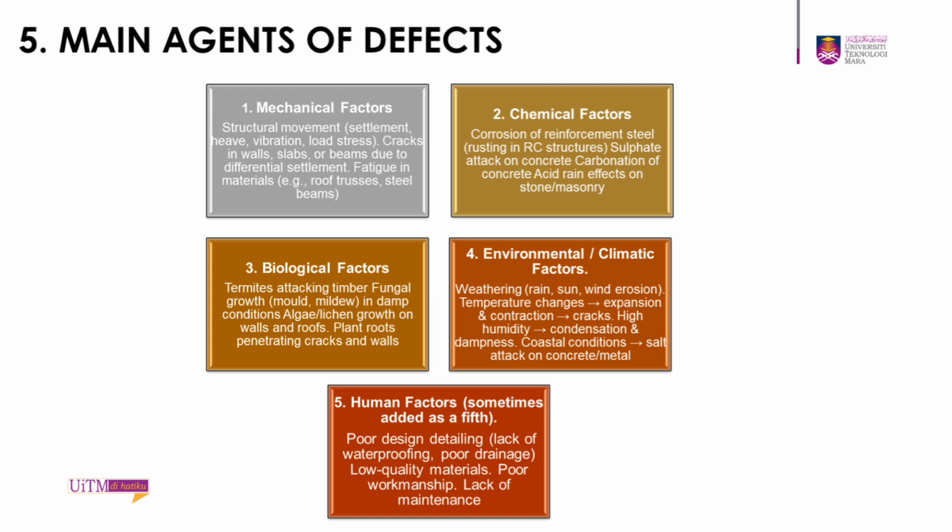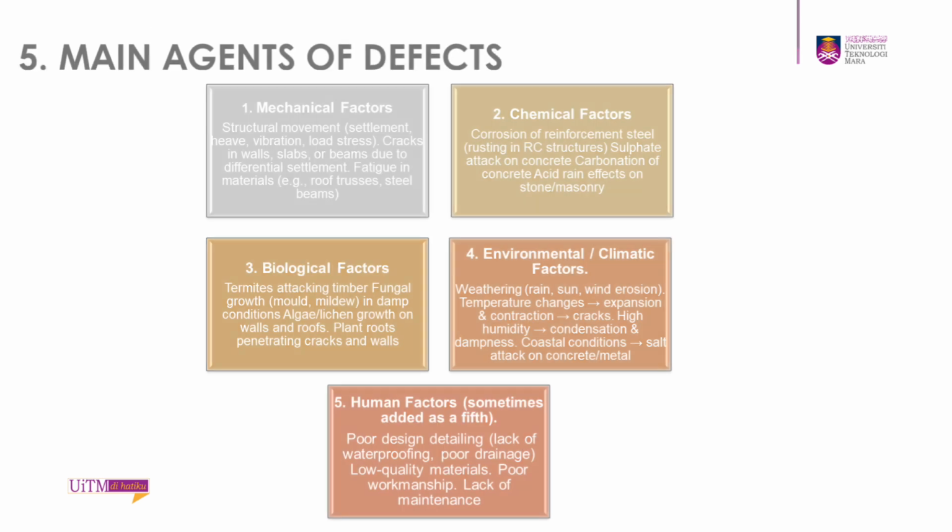4. Environmental, climatic factors: weathering, rain, sun, wind, erosion. Temperature changes lead to expansion and contraction, leading to cracks. High humidity leads to condensation and dampness. Coastal conditions lead to salt attack on concrete, metal. 5. Human factors, sometimes added as the 5th: poor design detailing, lack of waterproofing, poor drainage, low quality materials, poor workmanship, lack of maintenance.